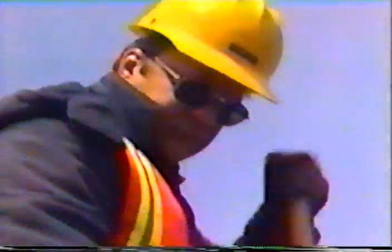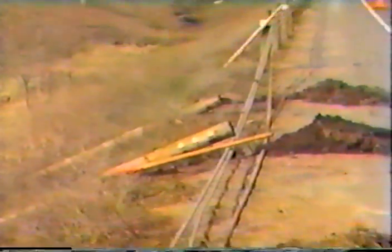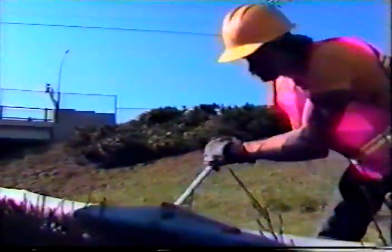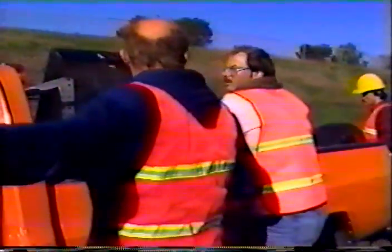You are often in the best position to observe when a guardrail system should be removed because the hazard is no longer there. Perhaps a sign has been removed or a steep shoulder slope has been leveled. Because a guardrail is a hazard in itself, it is important to mention when one no longer seems needed. In addition, it is also important to repair a partially damaged system to its original configuration because restoring to new standards may affect the functioning of the system. Again, mention should be made to a supervisor to determine if a change to new standards is merited at a future date.